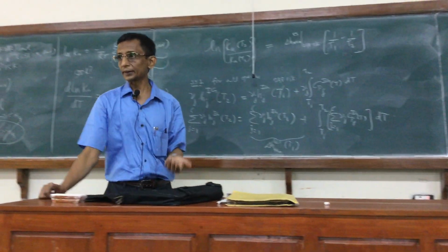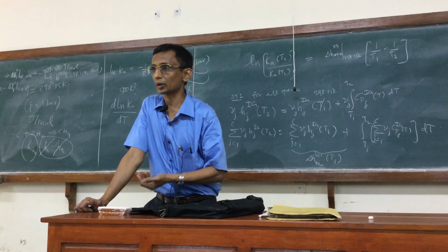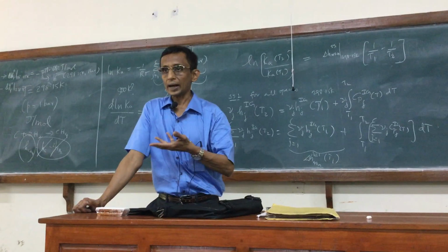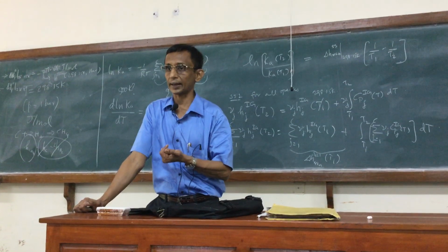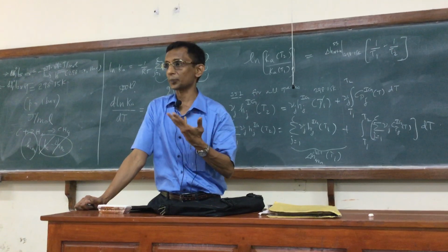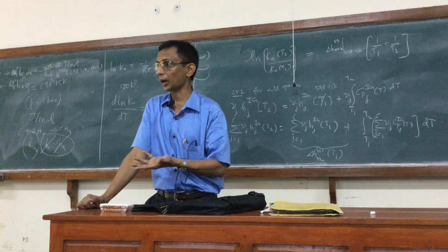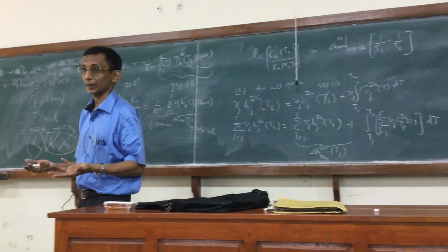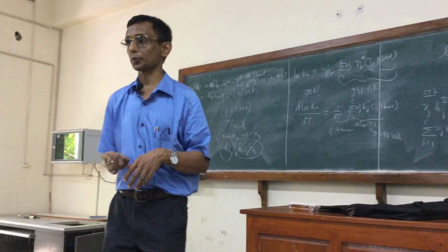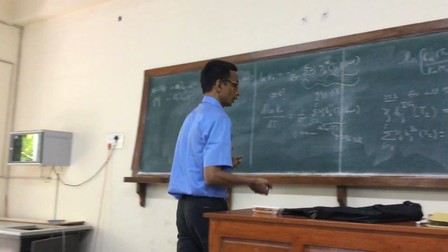If we take standard state 2, let us say, then we would need the specific heat because that would correspond to the specific heat which will be a function of temperature as well as pressure. It's no longer the ideal gas. What we need is that pressure to be at 1 bar. So we would need the specific heat data at 1 bar. But if we can neglect the change, which might be readily available because 1 bar is close to 1 atmosphere, and atmospheric specific heats might be available.